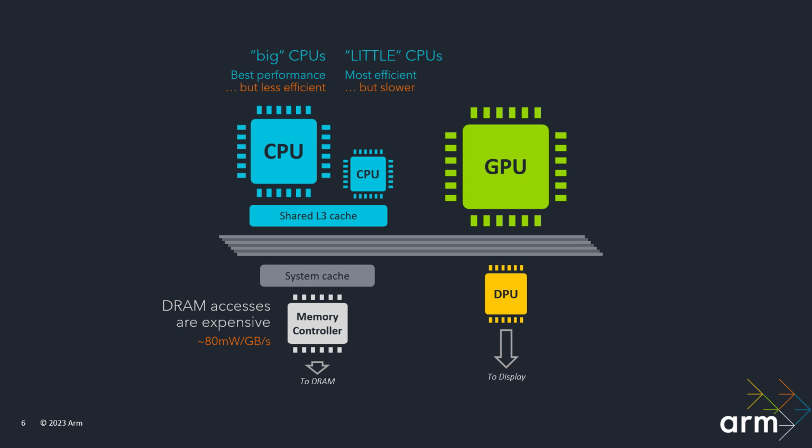But they are processors. They can generally handle some amount of composition. That's layering, scaling, rotation, color space conversion, and so on. However, they are hard real-time processors. They have to hit their scan-out deadlines or you get screen tearing. So if the workload is too complicated, the OS compositor may fall back to the GPU to simplify a complicated composition into a simple composition and then hand that to the DPU a little bit later. That obviously increases your GPU workload and the memory bandwidth. That may be an unexpected load in your system. It can also increase latency because you're introducing extra work that has to happen to get that frame out to the display.